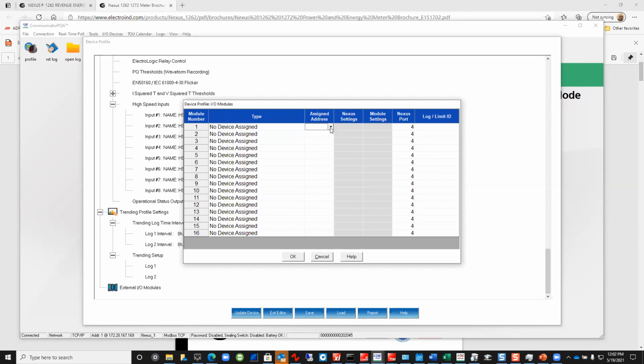Here they're addressable. Each one of these modules has a different address, and they would be connected on your 485 port, ideally. If you piggyback several modules, we recommend adding a PSIO, a separate power supply that we also sell, to provide the power requirement for those modules.